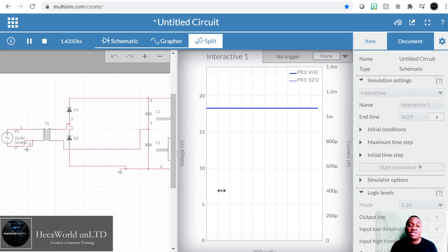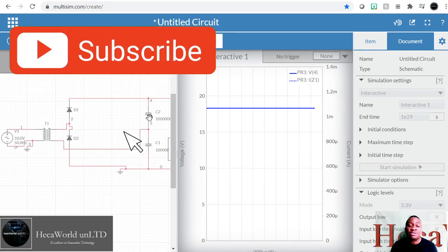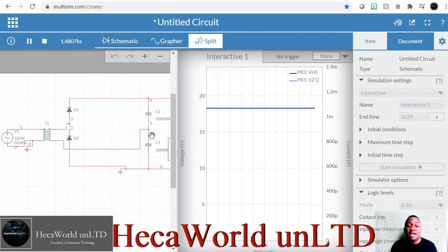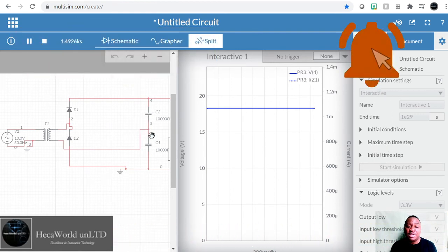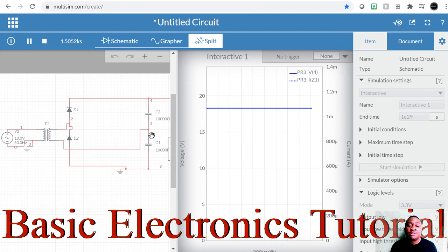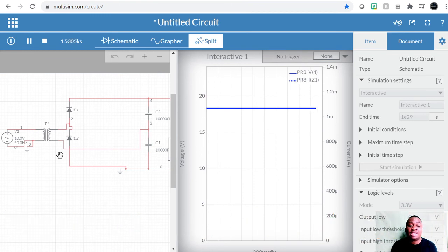So when the voltage is constant, which in this case it is, the only thing changing is our C. To get a higher C from the same V in the denominator, your I has to change, but I is not changing in our case. So the only thing that changes is the T. So it takes higher time to charge and discharge the capacitor, right? That's why you see this almost like a straight line.